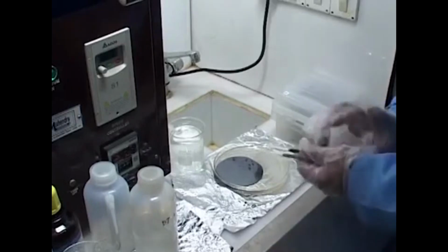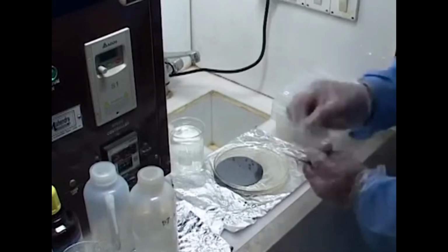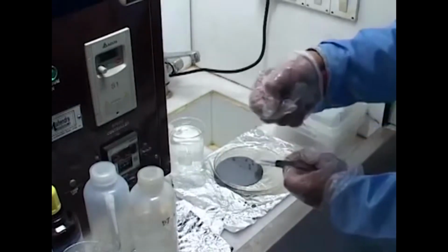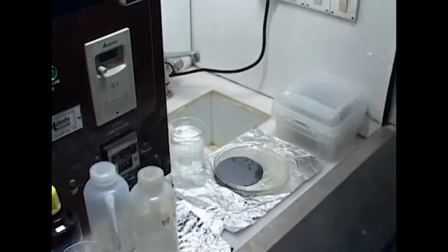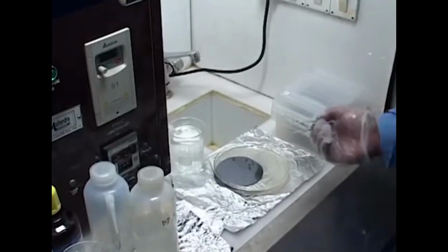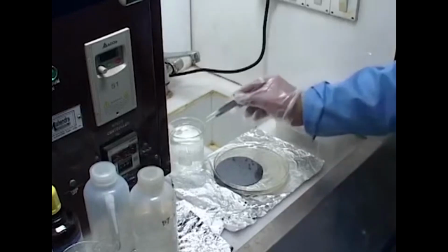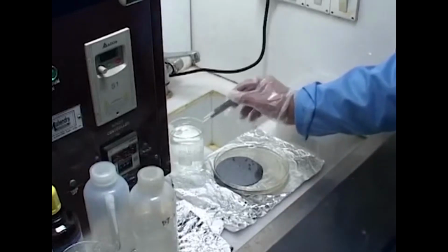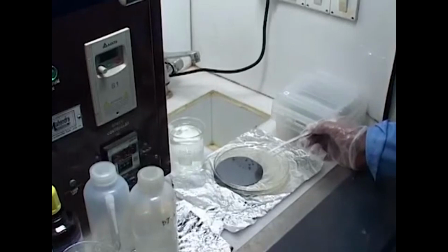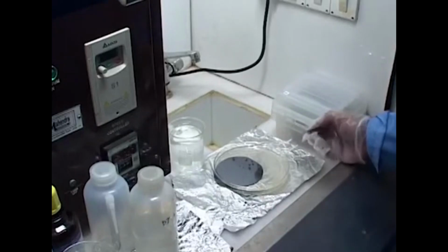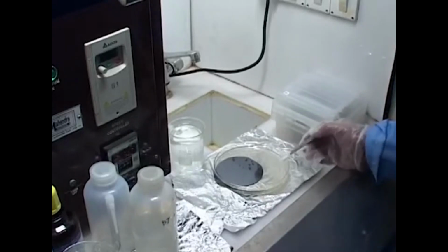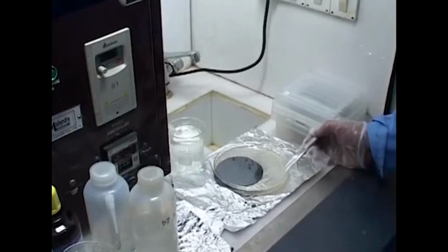So these, as you see, are now Teflon coated. These tweezers have tips which are coated with Teflon, or they can be complete Teflon tweezers which we can use. So what we are going to do is to provide a normal rinsing using distilled water, as you can see here, which is resting in the flask of this particular piranha clean wafer sample, and then this will be followed by another wash of deionized water, so that it gives a super clean surface on the wafer.